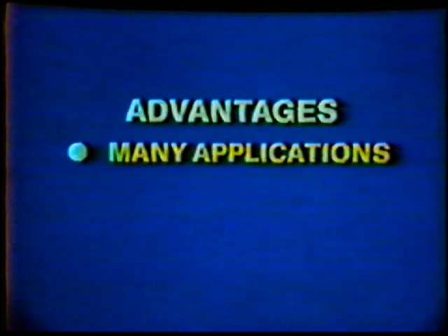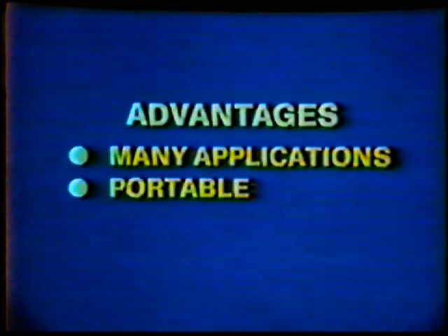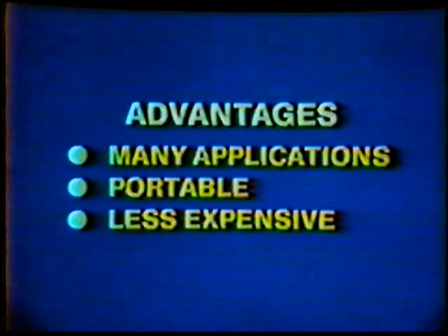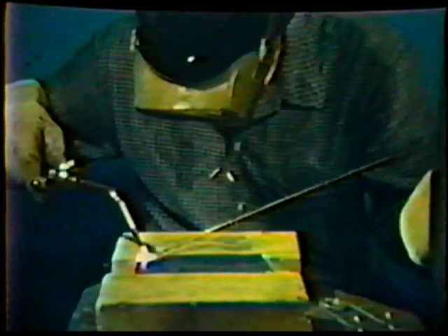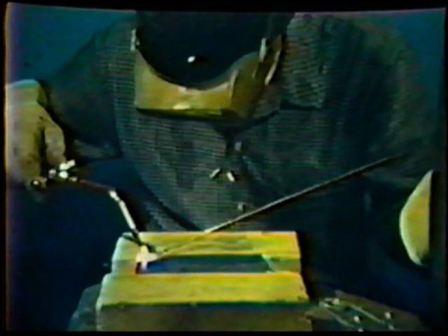The advantages of oxy-fuel welding are overwhelming. It can be used for many more applications than other processes. It is portable and not dependent on electrical power, as are the arc welding processes, and it is less expensive compared to other welding processes. However, it is a slow process to perform, requires much higher manual skill than most other processes, and the open flame creates a greater fire hazard.